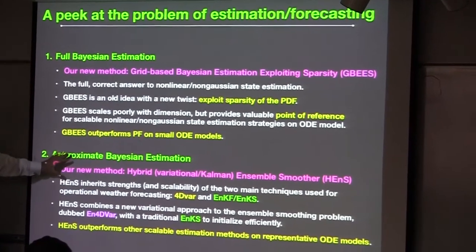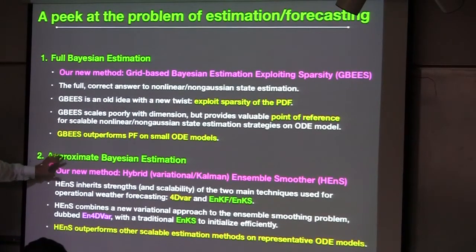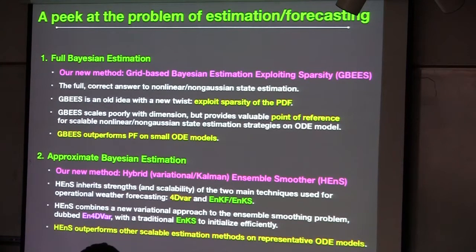The most common, of which 90% of you are familiar, is the Kalman filtering setting, and there are variations on that that are important, and the most important one to know is something called the Ensemble Kalman method, which is what scales to high-dimensional problems quite well. And if somebody teaches you instead that you should learn the particle filter, hopefully by the end of this talk I'll give you my perspective on particle versus ensemble, but this ensemble method, which was actually developed in the weather forecasting community, not the controls community, is a head and shoulders better method than this particle method, and I will get to my description of why I believe that in a minute.